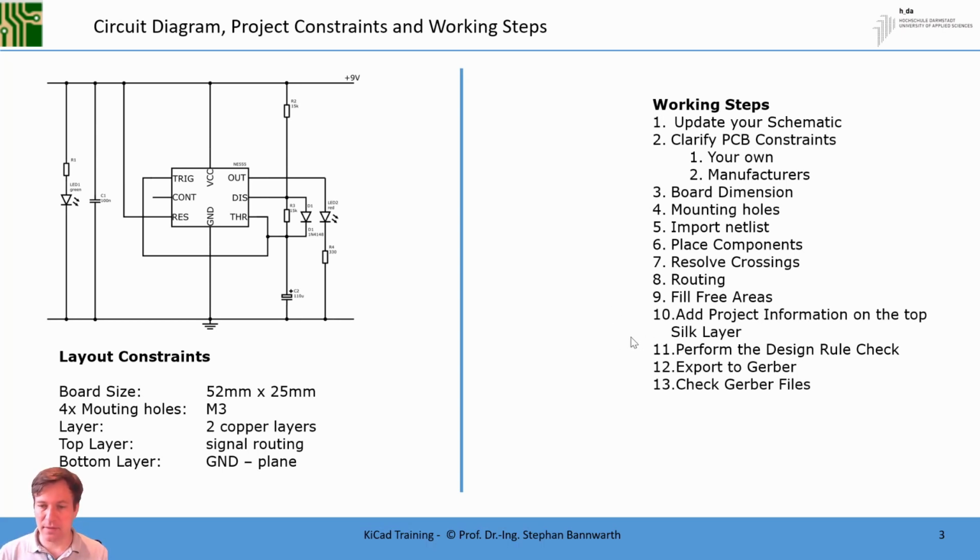Once this is all done, the PCB is more or less finished. You have to perform the design rule check. This means you check if you have followed all the rules of the manufacturer's constraints while layouting your board. So this check has to be finished with 0 errors before you export the GERBER files. So please take this very seriously. If you have any design rule check errors, please make sure you get rid of them before you export your GERBER files. Once you are design rule error free, export the GERBER files.